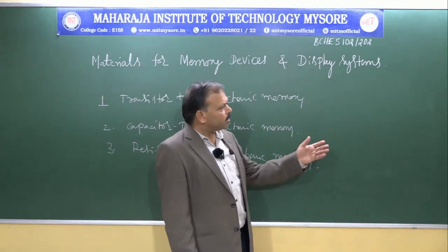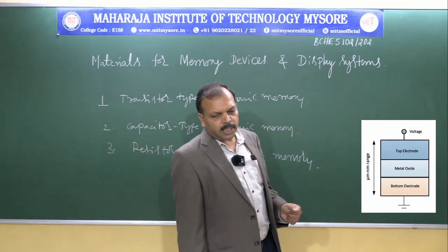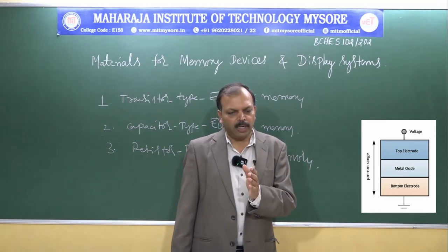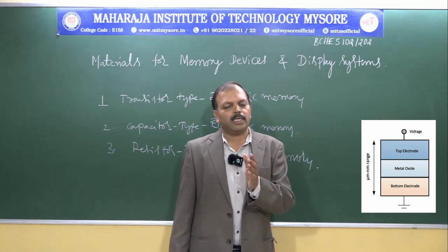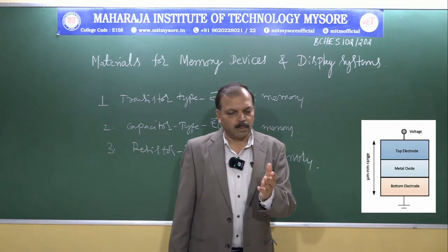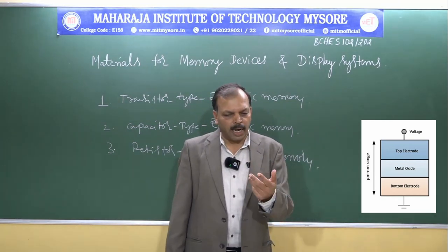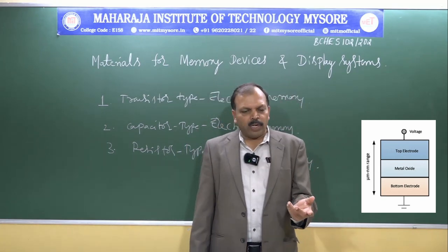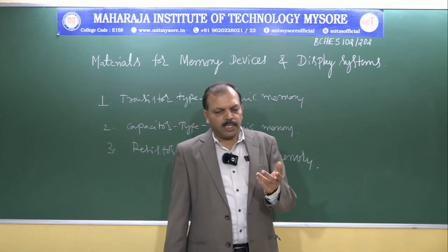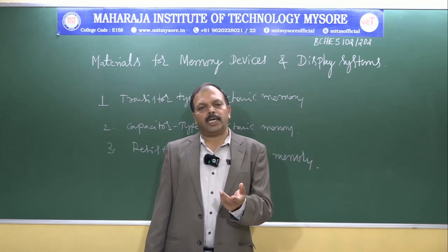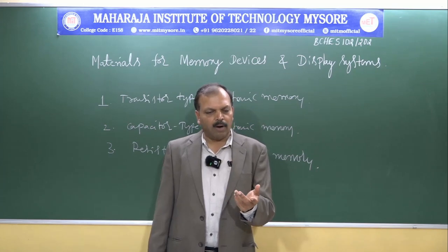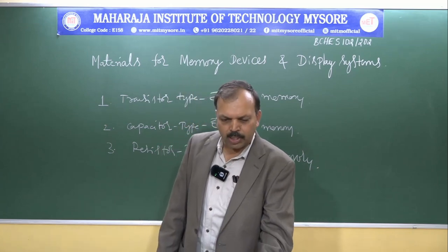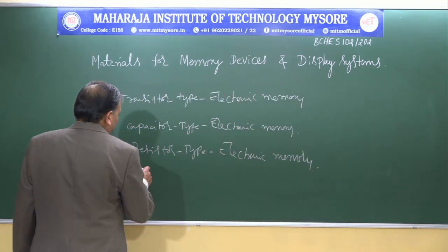The structure comprises an insulating layer sandwiched between two metal electrodes and supported on a substrate of materials like glass, silicon wafer, plastic and metal foil. The device is in a high resistance state, or off, logically the zero state, when the resistance is changed by charge transfer effects.